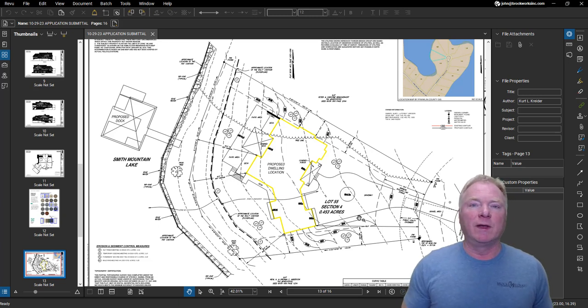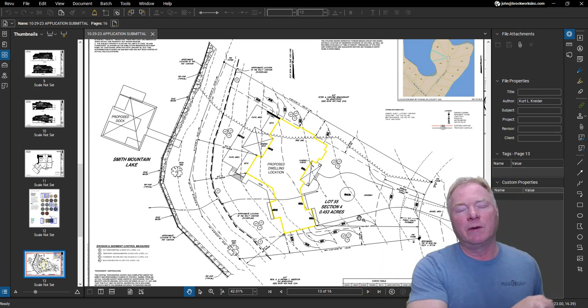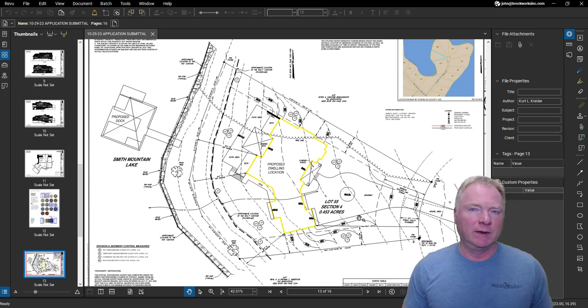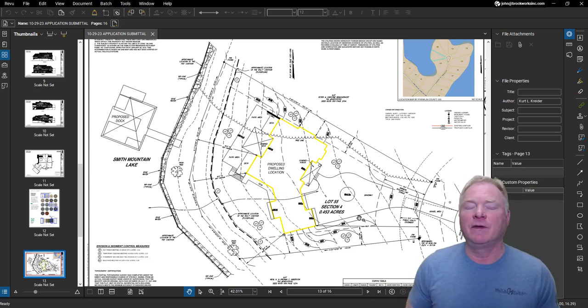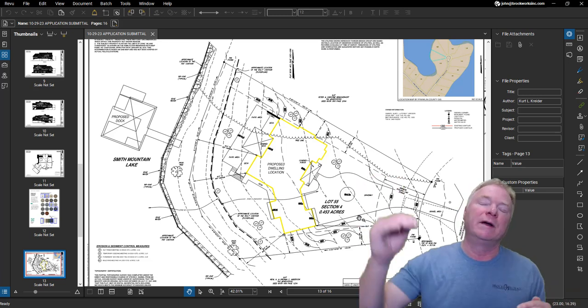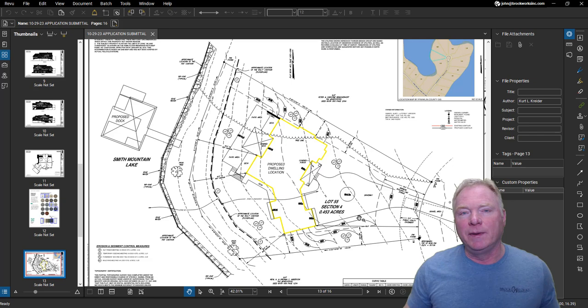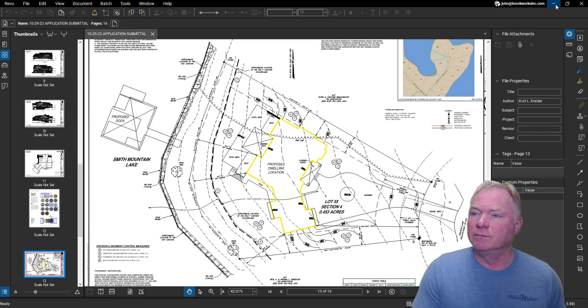Another option is if we have a relatively cleared lot, we have a Trimble RPT 600, and my guy Mason in the office goes out to the field, walks around with the RPT 600, and collects shot points. We bring that back over into SketchUp, and we use Fredo's Topo Shaper to create the 3D mesh for the surface. Now in this case, we've got a site plan that has contour lines, and I'm just going to recreate those by tracing over top of them and then moving them up into the Z-axis. Takes a little bit of time, but it's not that bad on a site like this. So we'll jump into it and get started.